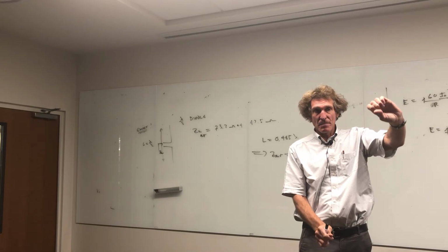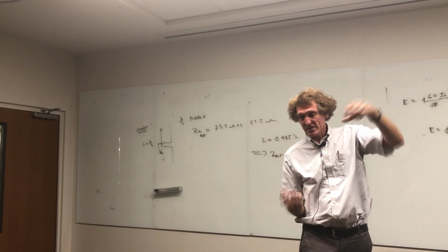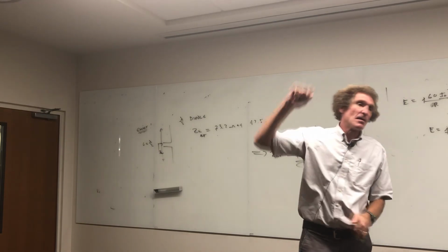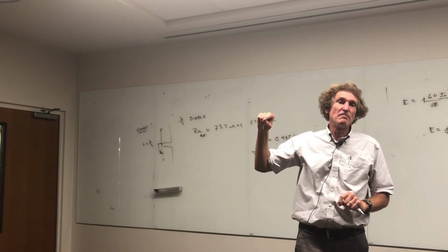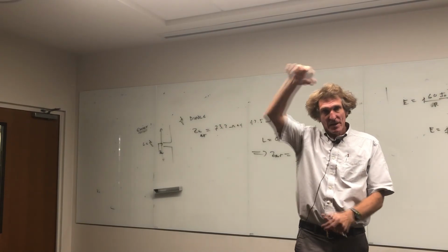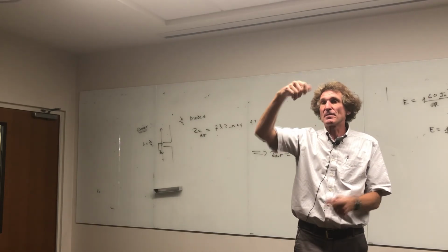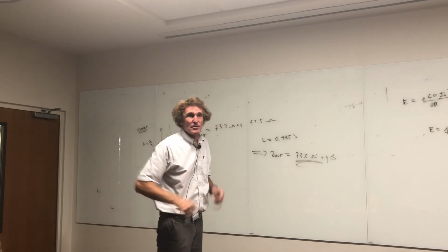You measure it, it's a half wavelength, right? You see that imaginary reactance. Take your nail clippers, snip off both ends, maybe just a millimeter off. You'll notice the input impedance falls down. Again, you start snipping, and pretty soon you get plus j0, you're done. And that's exactly how it's done in the real world a lot of times.